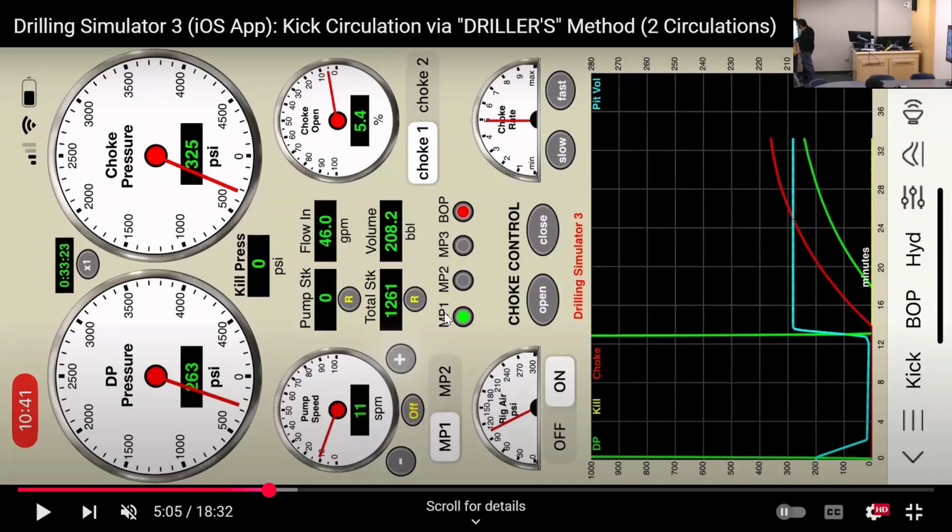Yesterday it was step 9 or something. You start increasing the speed, start pumping, and then opening the choke. Open the choke a bit more, pump more, until this becomes 40. This here at the bottom, that says 11, is the same as the strokes per minute. It's the pump, the circulation rate. It's the same as from the first screen.